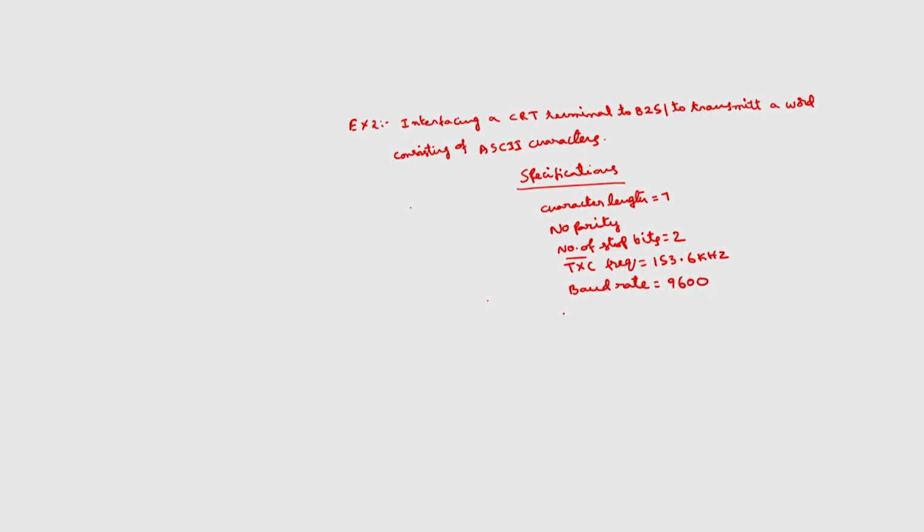So, we get the baud rate factor as 153.6 into 10 to the power of 3 divided by 9600, which comes to 16. So, these are the different specifications.